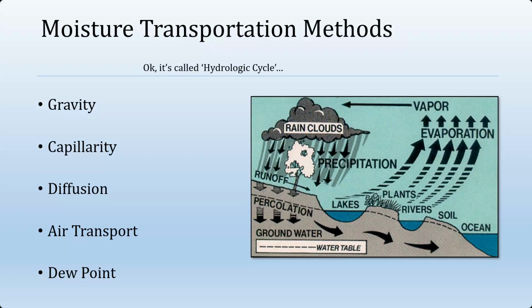If anybody watching has been involved in hydrothermal analyses, the dew point never occurs in a fixed static straight line. It's usually oscillating back and forth, but largely within the thermal layer. And if we place all that on the outboard side of our structures, that's where the majority of the moisture is going to occur, which is certainly where we want to keep it.